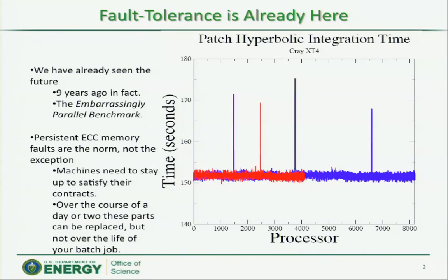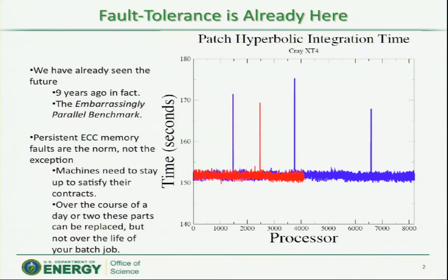But if one of the DRAMs goes bonk, it's still going to load, it's still going to come in. Since it's only a 1-bit error, you have an ECC code up near the processor at the end of the load stage, where it can detect the 1-bit error, does a little logic, and hands you back the byte. So you never see that this is occurring, but what you'll see is that I'm consistently accessing that piece of memory, and it's consistently going slow. For a particular machine, if it's got a bad bit of DRAM, it just takes a lot longer to show up. So you integrate this enough times, and you will see that tens of seconds get lost in that load time.